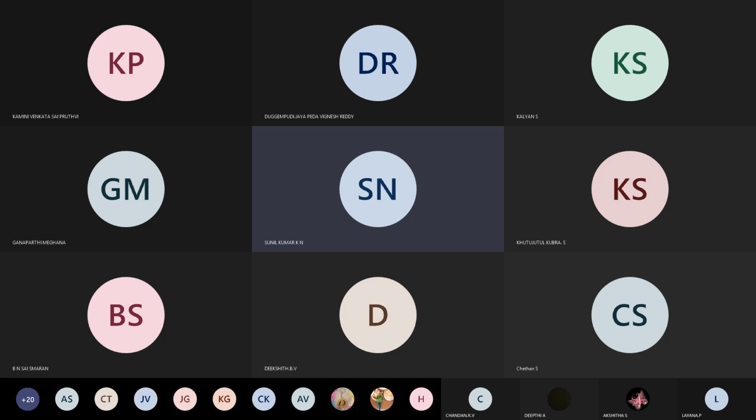The same thing we write here. Half Kn is common, and in place of a square we write VGS minus VT whole square, plus 2ab. The 2 gets cancelled, so half Kn into 2ab becomes Kn into VGS minus VT into vgs, and then we write the b square term: half Kn into vgs square.